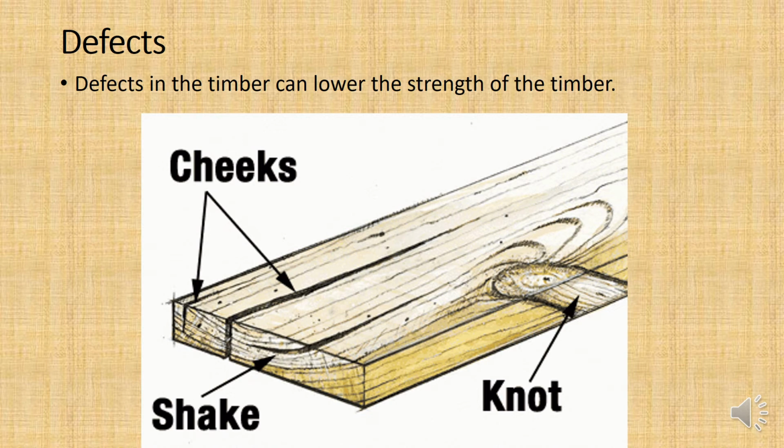You don't let the guy in the lumber and timber shop select the wood that he's going to give you, because if you do that, he's going to give you the timbers which have the most defects, the knots, the cheeks, the shakes. They reduce the strength. So that's another very important thing to look for when buying timber.